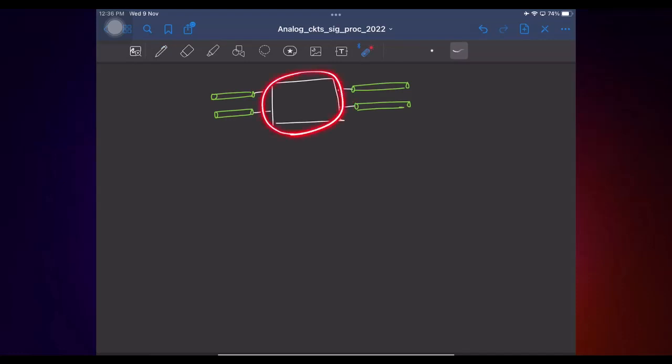No, this is some circuit that you have designed. Load should be transformed at the end of the transition. Okay, see, you think about it. Something goes here. I don't want that thing to get reflected back. Load should be transformed to Z0. No, say this has an impedance Z0. So something will go, but I don't want that to come back. It should appear as Z0. Yeah, so what can I do here? Matching network. Why matching network? Nothing. But eventually there will be some ZL at some end. It should be transformed to Z0. Just that.